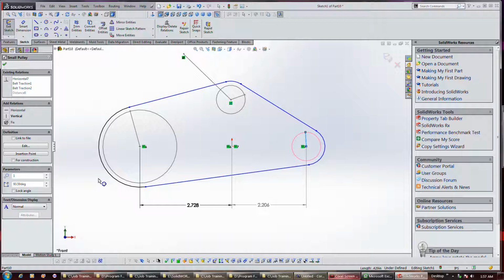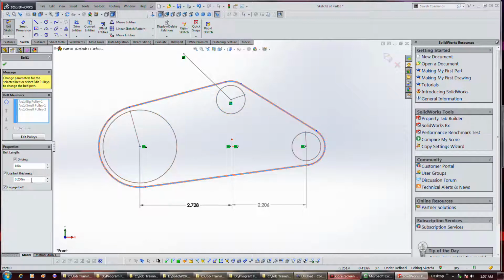And remember, the belt is still a fixed length on this too. So it's still a fixed 18-inch. So it's adjusting the position of this pulley based on this rocker to where it'll achieve a 16-inch length for the belt.